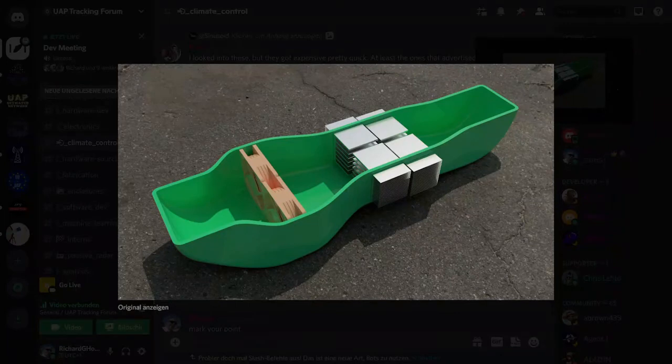You think it's feasible? But it is feasible. But before we get into that, we have to determine the final shape of it and how many Peltiers, the size of the heat sinks. Those have to be standardized, and then later on we have to standardize airflow because we can't be comparing apples and oranges with airflow. Yeah.